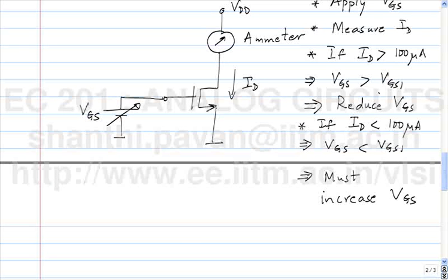the output current and just go on tweaking it, made absolutely no assumptions on the nature of the I versus VGS dependence. And it turns out that I have fooled you into thinking that the MOSFET is a square law device. In reality, it's neither square law, nor of the right form that I have discussed in class. This is just convenient for hand analysis. So the real function is actually a very, very complicated function. All right.